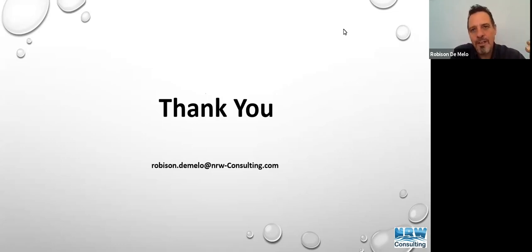So every 12 o'clock for every day, you average 12 o'clock from day 1 with day 2, day 3, day 4, up to day 30, and do the same for every 15 minutes. So you are averaging every specific time with its specific flow, averaging it into 24 hours. That, I believe, is it.